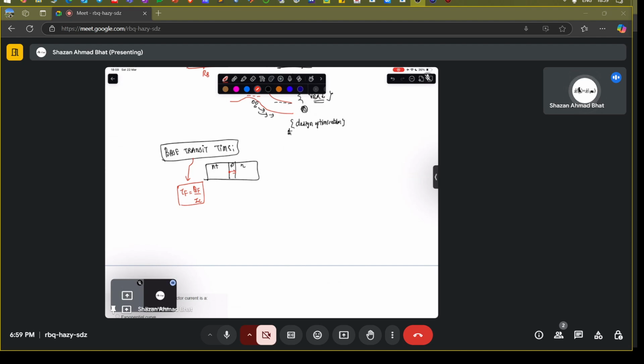So it's not the free charge, it's basically the minority charge carrier divided by the current which is flushing out the charge, because electrons are flowing in this direction. That's how the collector current is flowing. So that is giving you the base transit time. Or you can write the base transit time to be approximately equivalent to QF over IC, which is equivalent to WB squared over 2 times the diffusion constant of the electrons in the base region.